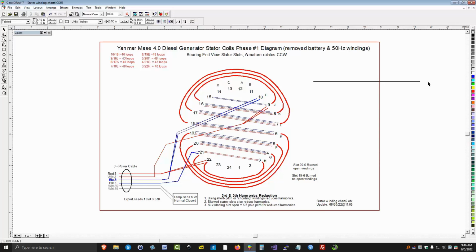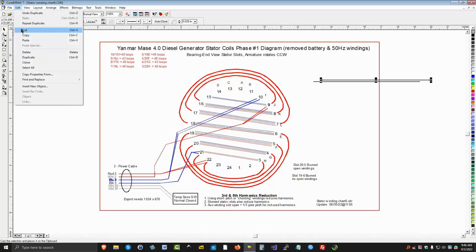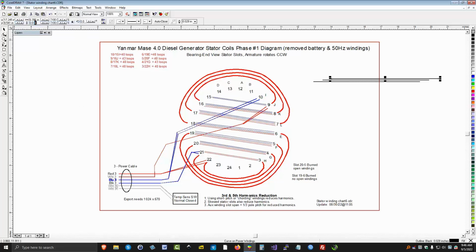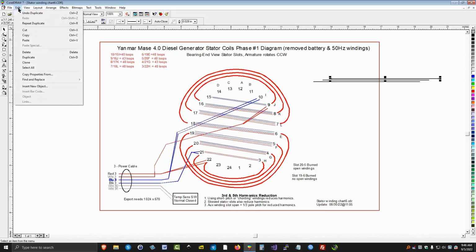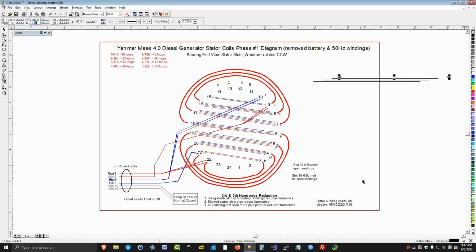I'll delete this last thing I did. So now I'm going to go back and reselect the tool. I'm going to do a Control D, which duplicates it in the manner I want it to by setting those offsets. And now if I go up here and use the tool, let's see. Repeat duplicate. It drops, you have to redo it each time. Control R. So I hit Control R, which means repeat. So that's how you repeat something.